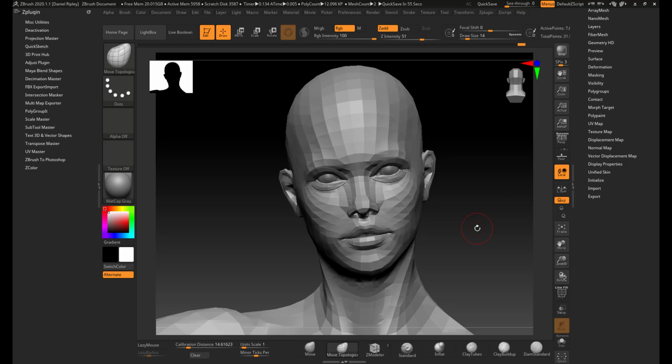This is why it's really important that you adopt a workflow where you scale the mesh first before you start to subdivide it inside ZBrush and start sculpting. So in other words, do your modeling, do your volume work even inside ZBrush, but don't do any major detail work. Send it over to your external application where you can accurately get the correct world scale of that character, and then rename. That's quite important. Rename the file so ZBrush has got no recollection of it ever being inside ZBrush before.